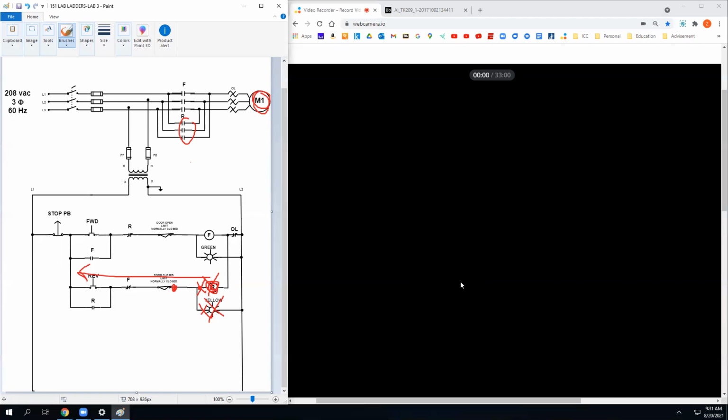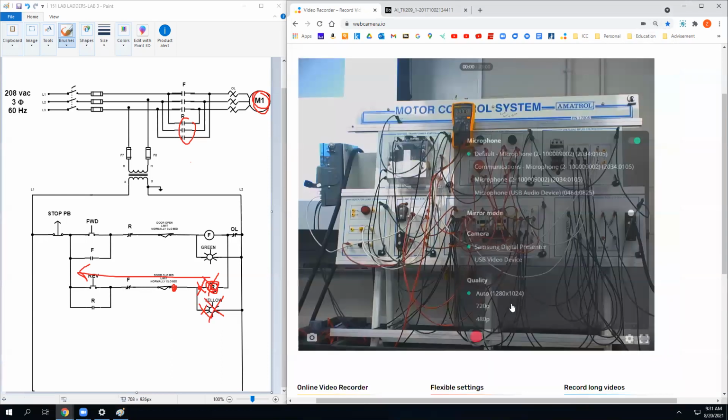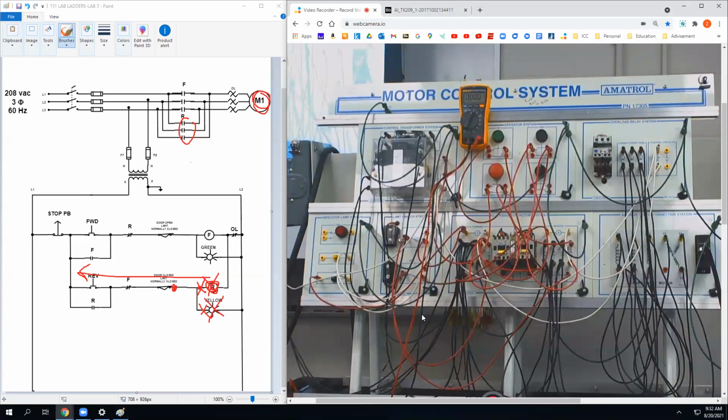Don't trust it. Even if we see the light is off, still don't trust it, check for voltage in there. So even if I know the control light is not working, but the light is off, if I see those two, I'm going to go check for a limit switch. What do you mean, don't trust it? Let's check it out before I go for the limit switch.